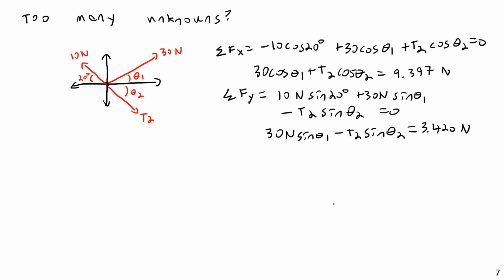Oh boy, there doesn't really seem to be a good way of solving this, does there? If I tried dividing these equations out by each other, well, that wouldn't work anymore. Basically, there is no way to solve these two equations. I could play around with these equations if I wanted to, but fundamentally, I still have three unknowns and two equations of equilibrium.